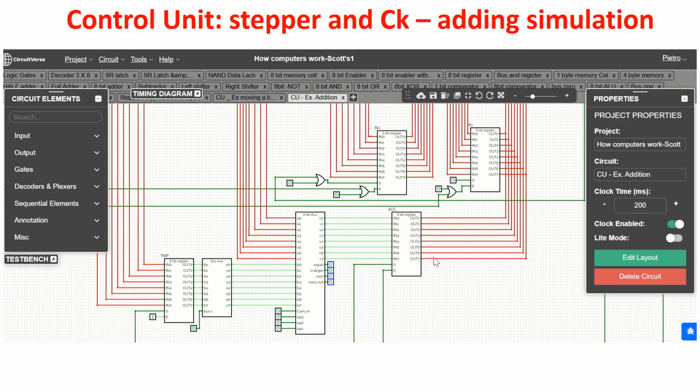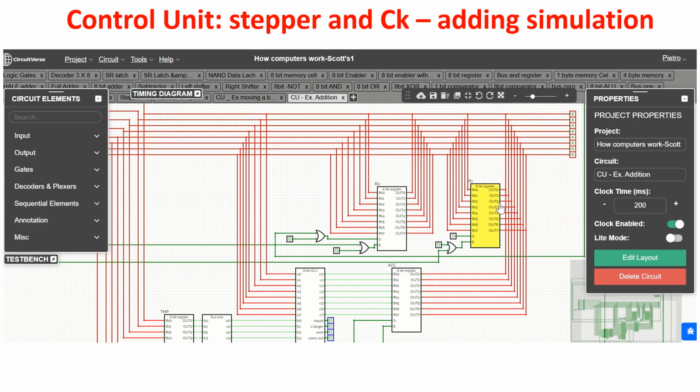This is performed in the fifth step. In the last step, I put the content of the accumulator on the bus and I acquire the content in R0. So in this way, I performed R0 plus R1 and I put the result in the register R0.